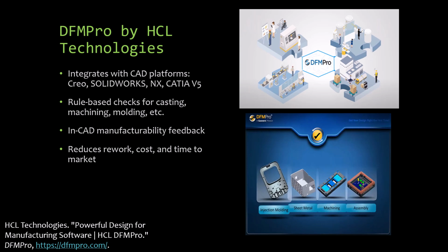For instance, the issues with injection molding are wall thickness, cutout area, boss parameters, rib parameters, mold wall thickness, draft angle, and min and max walls, and the rules that they have in the software check for these issues. The software alone offers early visibility into the manufacturing and cost implications that enables designers to make informed decisions that reduce rework, manufacturing cost, and time to market.